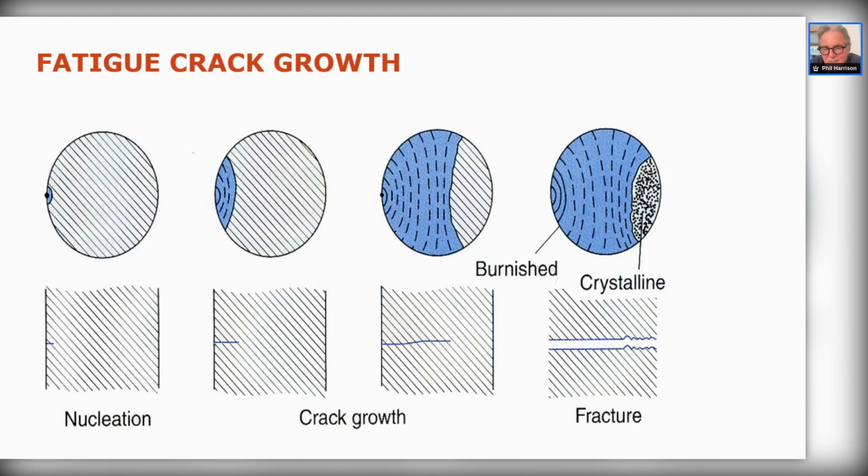Quite frequently, you don't always get these nice striations on the surface because obviously it's a failure. Things can start pulling apart and start hitting each other, so they can get leveled off. And again, looking at the nucleation side, you can see there, if we have a surface defect, the nucleation stage has been overcome. Next slide, please.